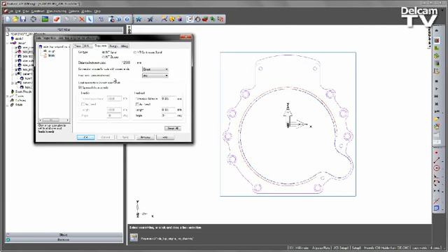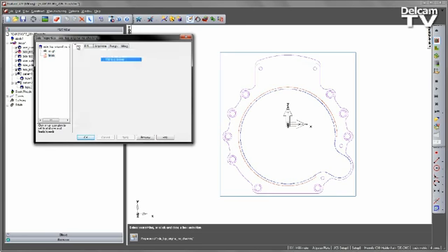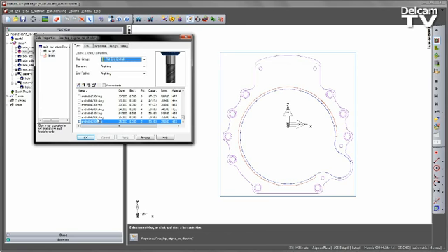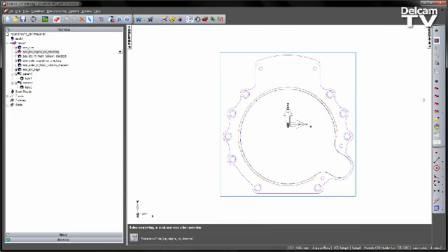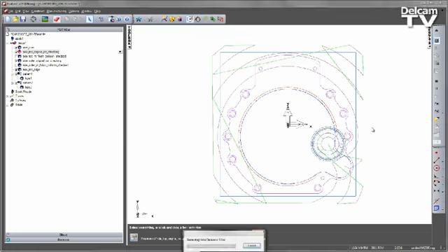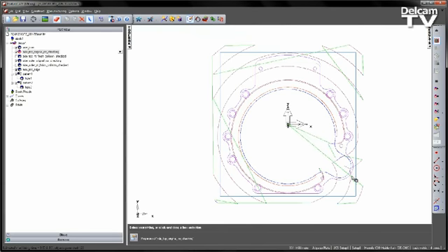As well as this, if I go to the stepovers area, in this case I can set a large stepover. At the moment the tool we're using is the largest metric tool I have, which is a 25mm end mill. If I go to my stepovers, set this to be a large value, for example 25, apply, and preview the toolpath, you can see in areas where there is the largest stepover region we get a move that tries to clear the material out.